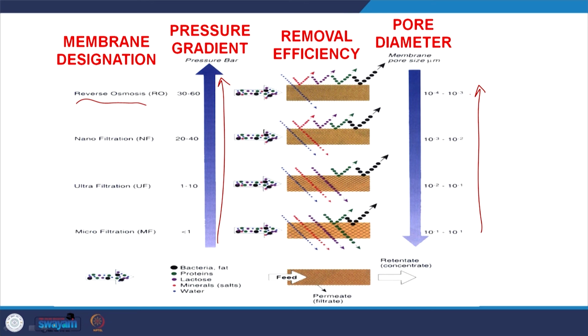Microfiltration typically will remove bacteria and bigger particles, certainly suspended particles, most of the suspended particles in this range. And ultrafiltration will remove, I guess they are saying proteins, but in general even some viruses, not all will be removed, and any bacteria that is left will be removed by ultrafiltration certainly. So, these are the two aspects we are going to be concerned about, let us say, right. So, let us go forth.